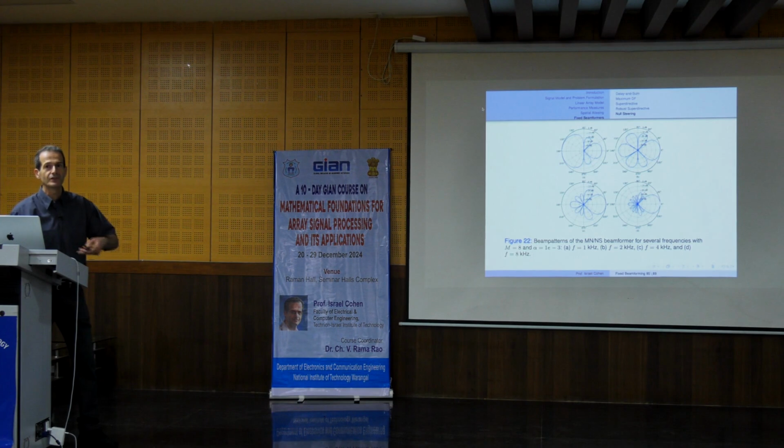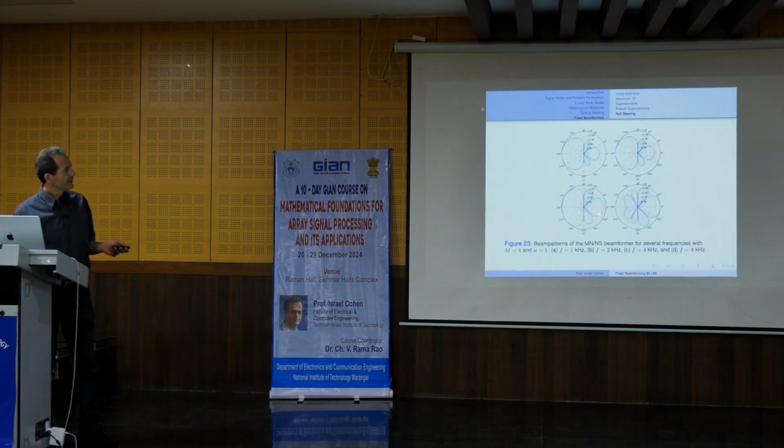Now if we further increase it to alpha equals 1, you see that the main beam becomes wider, but we may also have some side lobes, especially for low frequencies, that are even larger and give a larger directional gain for other directions, which is not good. Which means that the beamformer that maximizes the white noise gain can also decrease the directivity factor significantly.